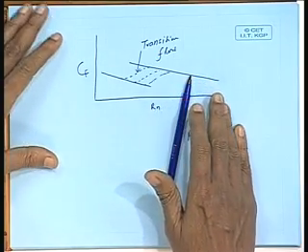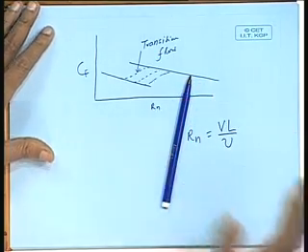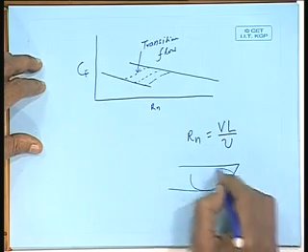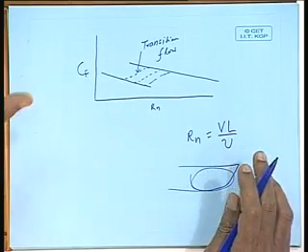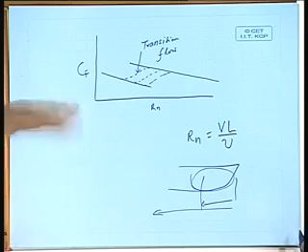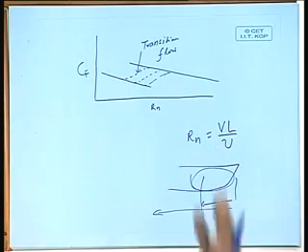Also, we have seen that the fore part of the model, where the flow is just starting to develop the boundary layer, the local Reynolds number, that is flow from the beginning till that position, somewhere here in this region, turbulence has not taken place yet, because the length here is much smaller than the whole length of the model. Do you understand? So, in the initial part of the ship, there may be existence of laminar flow. Initial part of the model, there may be existence of laminar flow over quite a region.